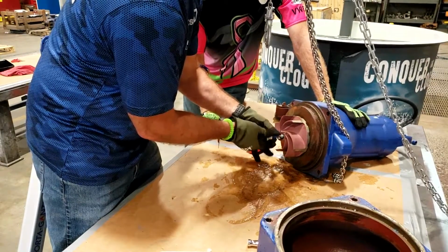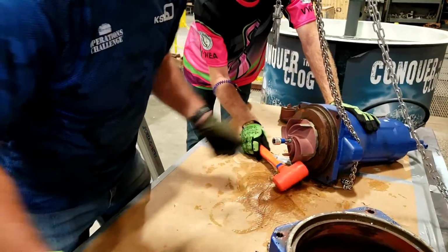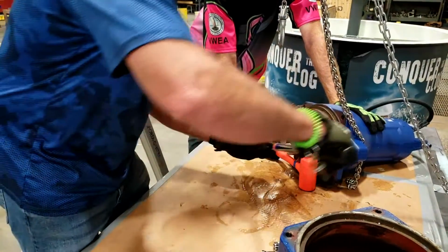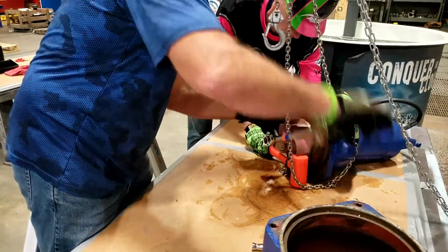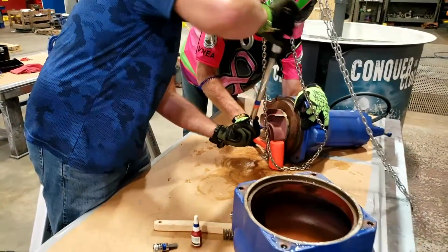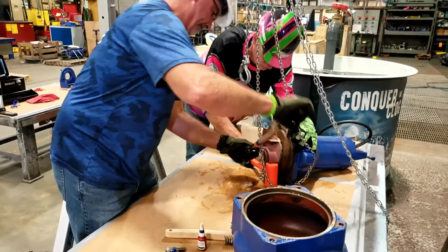You will tighten the impeller down with the standard ratchet until the impeller begins to spin. You may not have the impeller blocked while using the standard ratchet. When you are ready to use a torque wrench, then block the impeller with a dead blow hammer. Be sure to use the correct torque wrench.